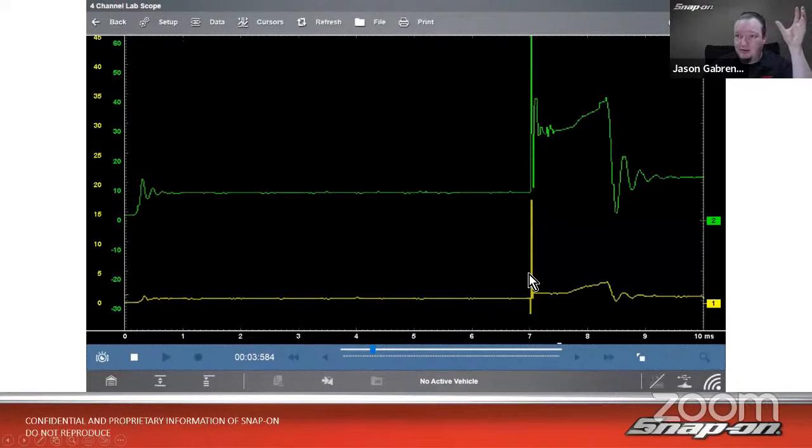I can't see actually, oh, this is like 60,000 volts or 30,000 volts or whatever it is. Versus on the secondary side, depending on how the coil's set up, and we'll talk about that in a little bit too, it gives us a lot more detail. We can see a lot more nuance in the signal. You can actually see that it's curving up considerably at the end, and I have quite a bit more oscillations there. So it basically just amplifies what we're seeing on both sides, because once again, that's the step up voltage from the primary circuit to the secondary.